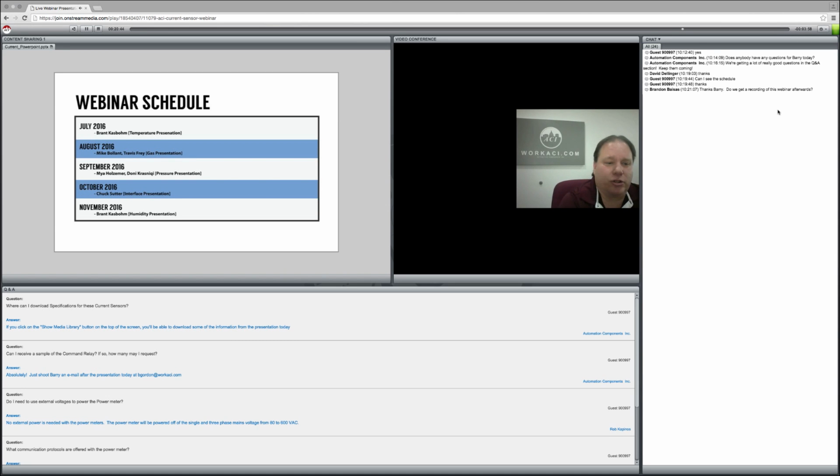Yes. You should be able to monitor if a fridge stops working as long as the current is above the minimum trip point of the current switch itself. In many cases, the way we spec our trip points is that it's the worst case. Let's say if I bought 100 CTs, it's the worst case that it'd trip at. So when we spec a 0.2 amp trip point, it could trip at any point between, let's say, 50 milliamps and the 0.2 amp range. So as long as your current's above that minimum trip point on a go, no-go type current sensor, you should definitely be able to see the output tripped at any point.